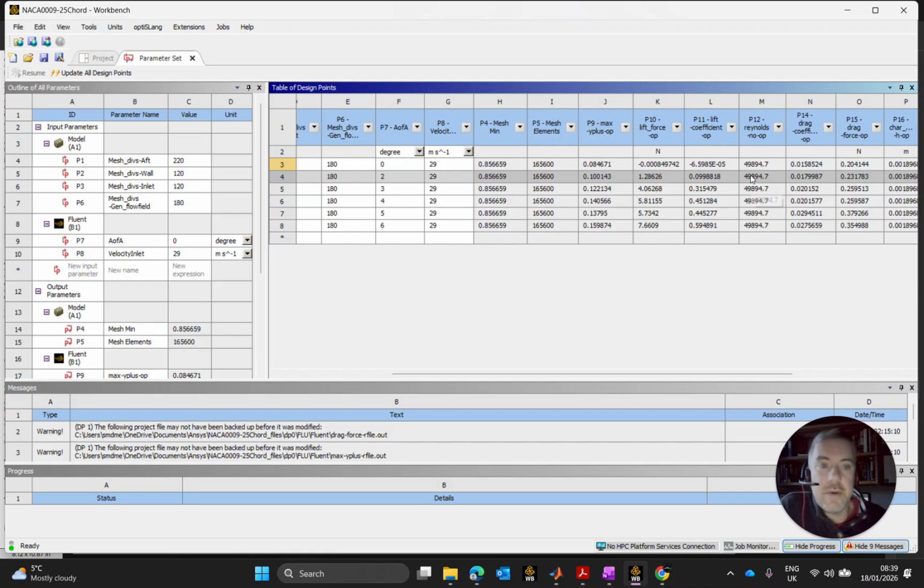So I overestimated, which resulted in the Reynolds number being somewhat smaller than the target Reynolds number. However, with such a small relative difference, our results should be comparable. But I definitely would want to sharpen that up and tune either my velocity or my dynamic viscosity, or even make my density slightly larger, to get the Reynolds number that I want.